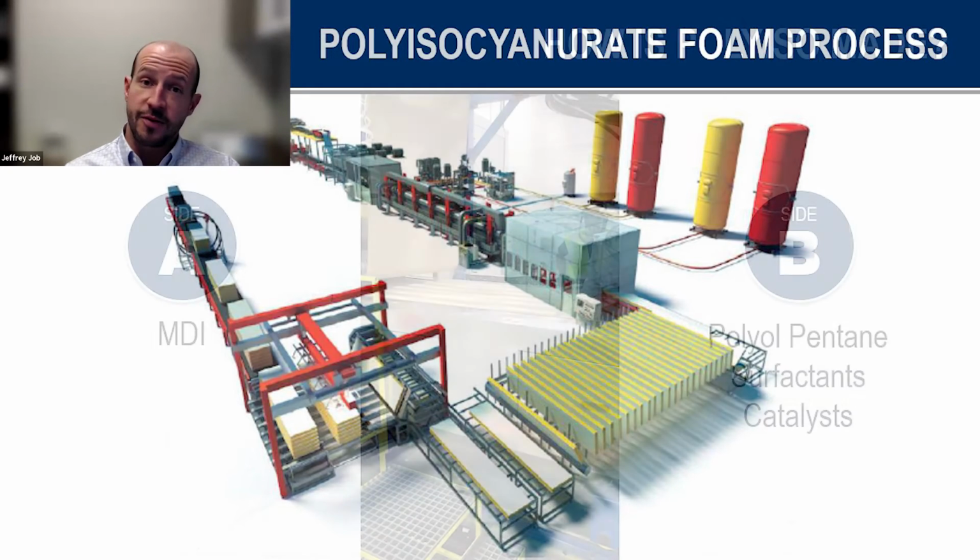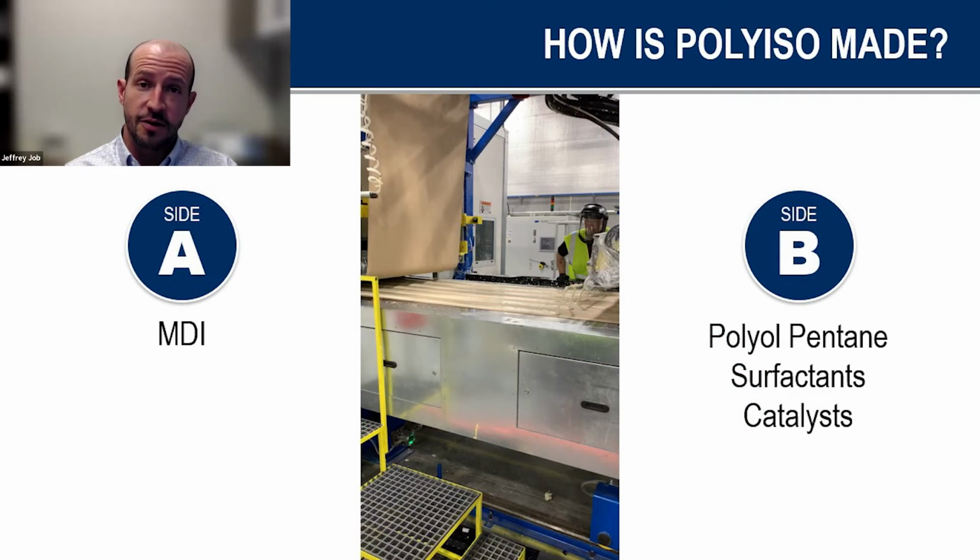A lot of other benefits related to that CGF facer include its ability to work with adhesives really well. So if you're doing an adhered job, that tends to be the facer of choice. One, because it won't absorb as much, right? We just talked about it's going to resist water absorption. For example, on a paper facer, if you're using adhesive, that paper facer can soak up some of that adhesive, and you will typically not get as good of coverage rates as the literature on that particular adhesive might say.